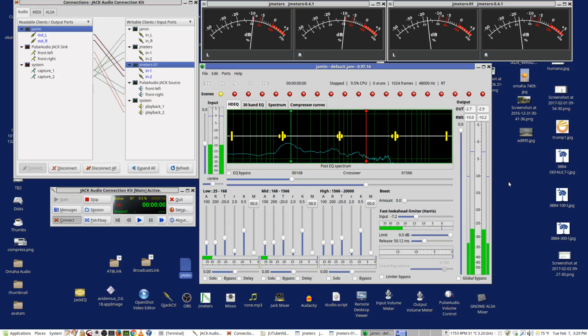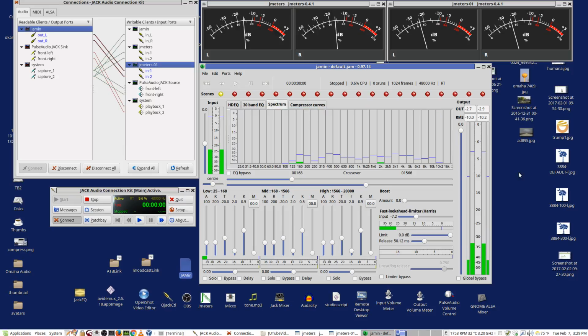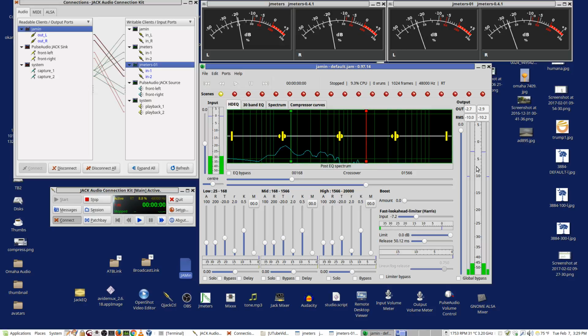All right. Let's go over to the spectrum and try that again. See what the spectrum does. Remember, it's a 1K signal. Now you can see it came in at the 1K mark. The right bars over here, those are the output bars. And you'll notice that they only go up to a certain point once you've limited it. So, all right, so I now have a couple of things working.